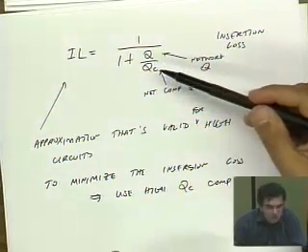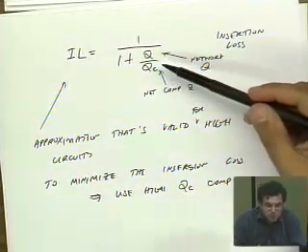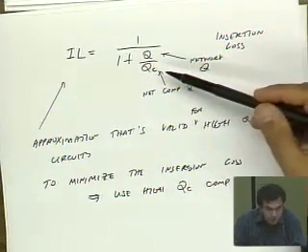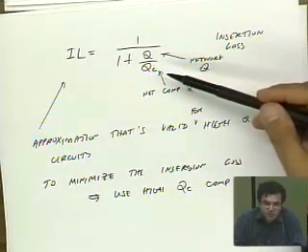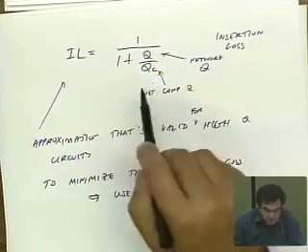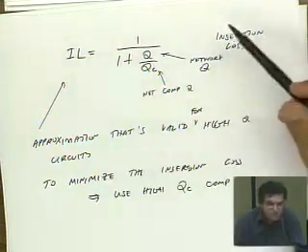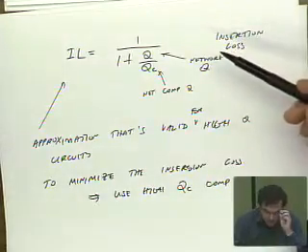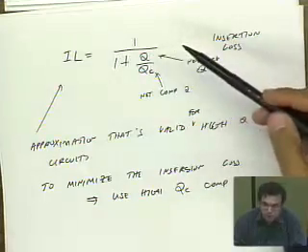It's not going to matter that much. It's a marginal difference. On the other hand, if someone says my network quality is 100 and I want to use components with a quality factor of 100, you can see right away that the insertion loss is going to be more than 50%. So it really matters what network Q you're trying to achieve.